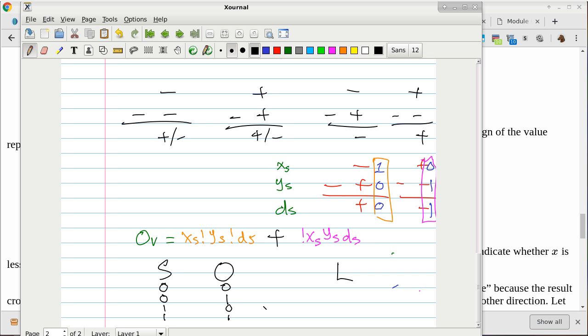Let me say that one more time. When the sign flag is a 1, it's telling you, oh, guess what? The minuend is less than the subtrahend. But then you look at the sign flag with a little bit of skepticism, because sometimes it lies. So now you check with the overflow flag and say, is he lying? If the overflow flag says no, it's good, honest, then you can trust the sign flag. So if you trust the sign flag and it says it's not less than, then it's not less than. So the L flag says, okay, it's not less than.